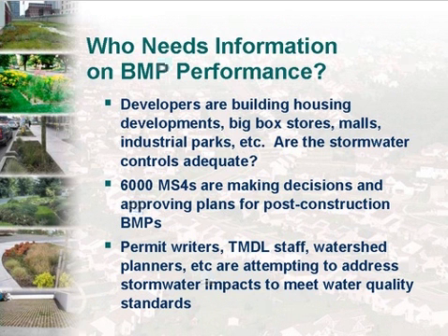We also have some 6,000-plus MS4s, which is Municipal Separate Storm Sewer System, for those who don't know. In our lingo, it's the communities that are regulated under Phase 1 and Phase 2 of the NPDES stormwater regulations. And those communities, particularly the ones in the Phase 2 regulations, are bringing their programs online right now, and they're going to be reviewing post-construction plans and BMPs and hoping to guide development to be as stormwater-friendly as it can be. And so we're hoping to provide lots of information for those MS4s so that they can do that job.